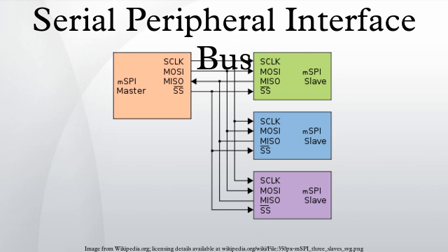Transmissions may involve any number of clock cycles. When there is no more data to be transmitted, the master stops toggling its clock. Normally, it then deselects the slave. Transmissions often consist of 8-bit words. A master can initiate multiple such transmissions if it needs. However, other word sizes are also common, such as 16-bit words for touchscreen controllers or audio codecs, like the TSC2101 from Texas Instruments, or 12-bit words for many digital-to-analog or analog-to-digital converters.